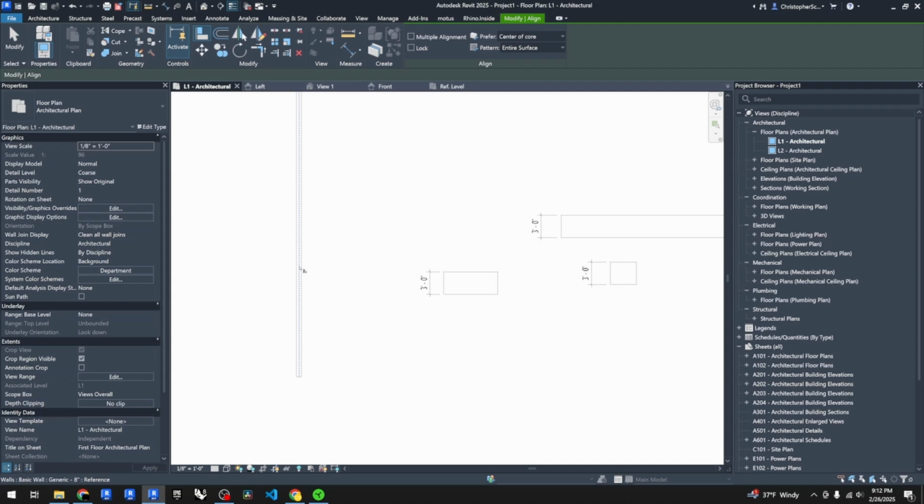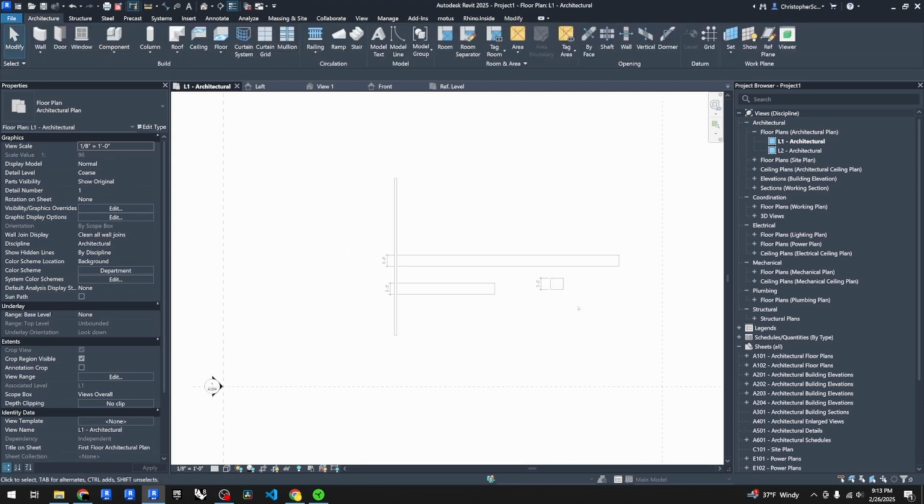So now if I align the outside to this, we can see it moves that entire reference plane. So a weak reference plane will move the entire object over. A strong reference plane will essentially flex the whole model to match or to align. So a big difference there.